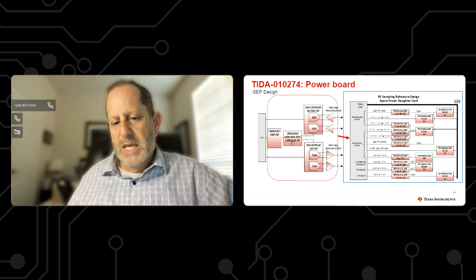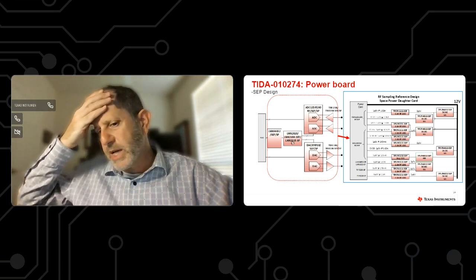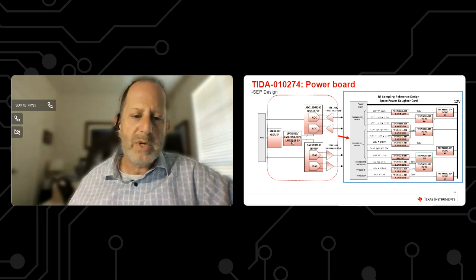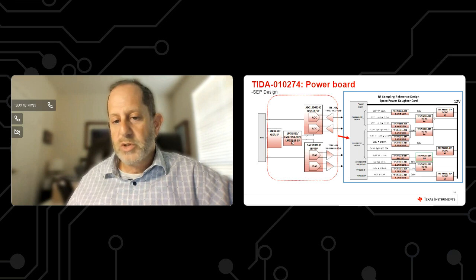So this is a key angle when we're talking about these RF transceiver systems, is we've got to be cognizant of the power supply. We don't want noise that's coming in from the power supply side of things to infect the analog performance. So we've taken a lot of care in not only designing with the proper parts that are low noise, but the proper layout as well, so that we don't have switching supply spurs from one switcher infecting a sensitive analog rail that might end up getting into a converter and then causing some problems.